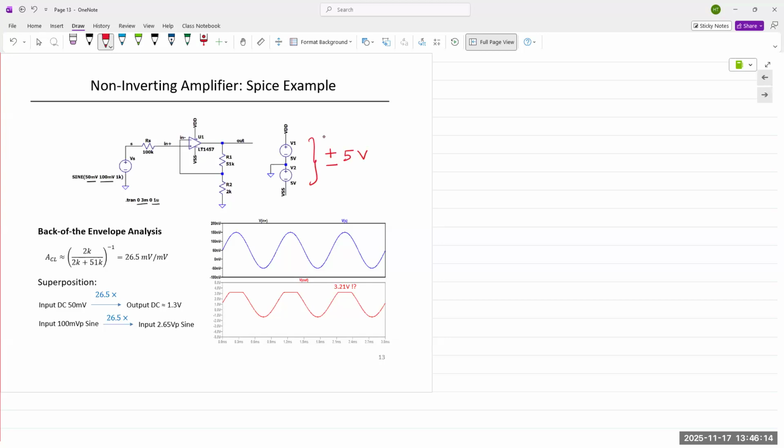This is another way of doing LT-SPICE where, instead of doing cross connections of complicated circuits, you break it up into individual parts and you simply name those terminals. And it automatically makes the connections. Okay, there does not have to be a physical line joining them.